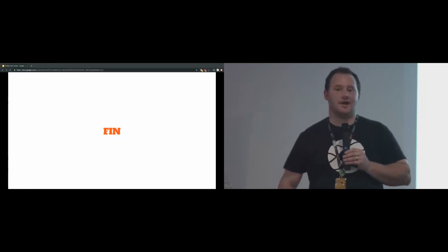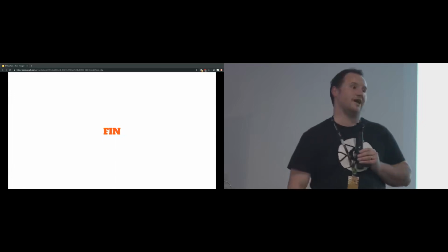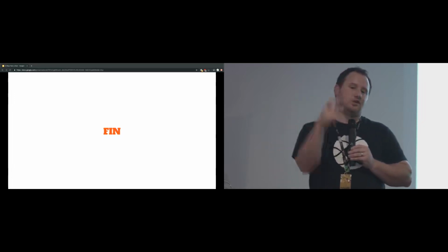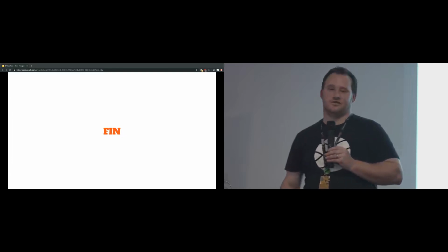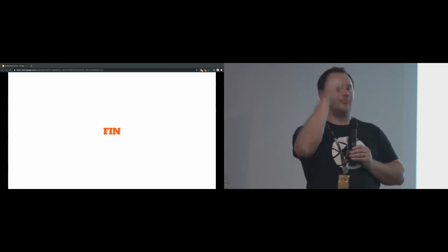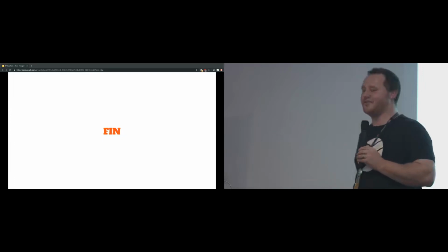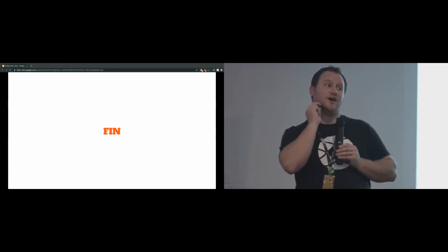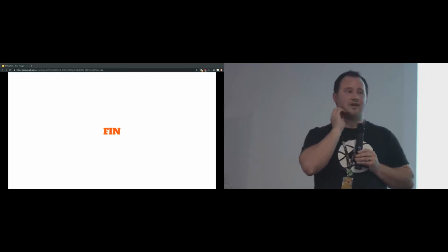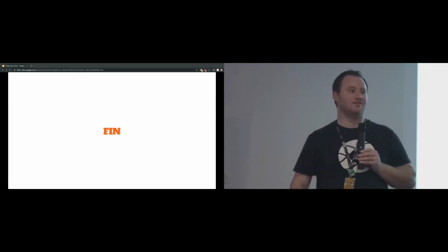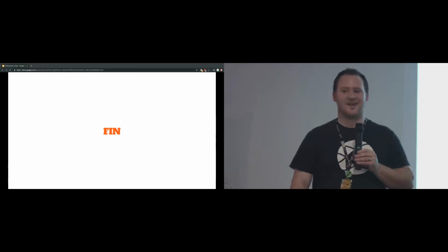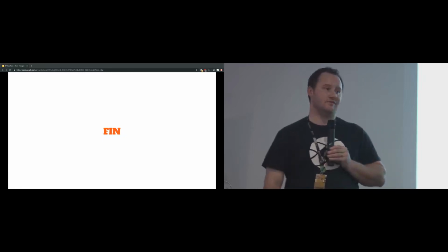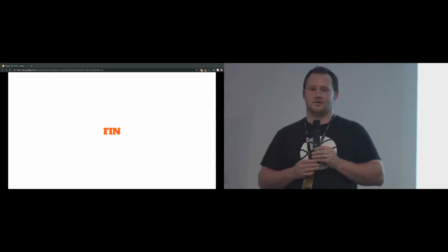It's a very low tech attack. If you have external hinges and they're not security hinges where the hinge pin is welded at both ends, you just get a nail punch and you punch the pin out and then you open the door backwards. I've never had to do it. It's totally a viable attack. Rehanging the door might be a massive pain in the ass, and that's something I try to avoid because I'm lazy. Yeah, it's another one to have up your sleeve. Absolutely. Anyone else?